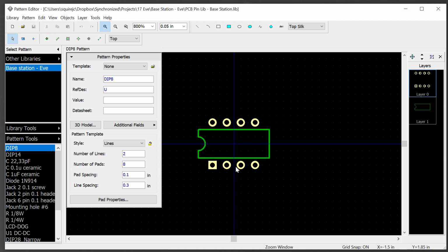The solder pads may be the same size, or they may be different. Most patterns use a differently shaped solder pad for the first pin just to identify it as special. Each pattern holds 2 other pieces of information. The first are the size of the drills used.